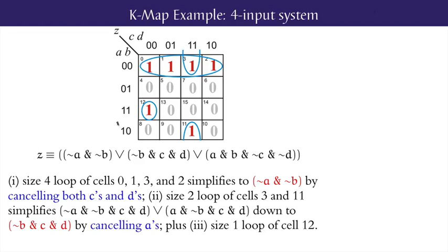The ABCD code of 1100 tells us that this conjunction is A and B and not C and not D. The resulting minimal DNF circuit, which you can draw on your own for practice, has an outer level 3-input OR gate and at the inner level a 2-input AND gate, a 3-input AND gate and a 4-input AND gate.